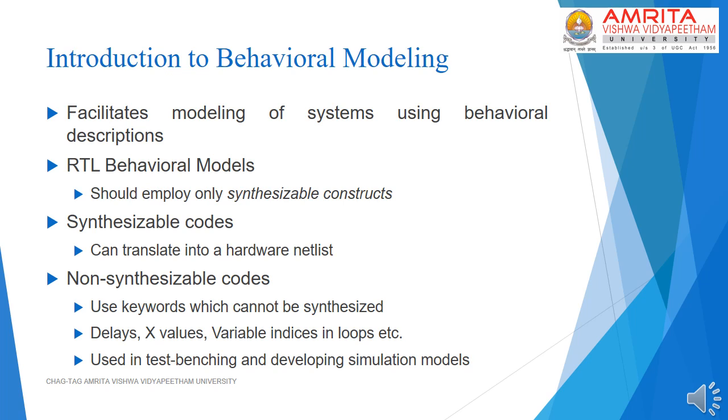There are a lot of non-synthesizable constructs which are also provided in hardware description languages like Verilog and VHDL. These include delay constructs, X values in assignments, and variable indices in loops. These constructs are primarily meant for verification. They are required when we write test benches and also simulation models which are used to verify designs.